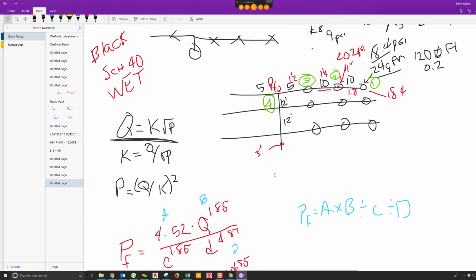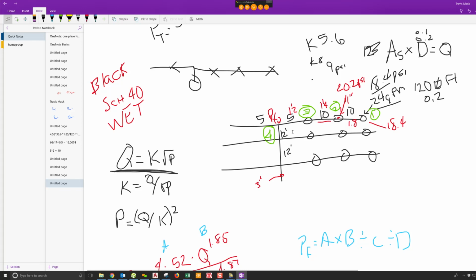And with this, you can kind of see something. You start to get an understanding as you grasp things: this is why, if you're doing 0.2 over 1500, you will never get exactly 300 gallons per minute, because there's going to be some friction loss somewhere. And anytime there's friction loss, that means there's greater pressure at the orifice closer into the system. So with greater pressure, it's going to cause bigger flow.